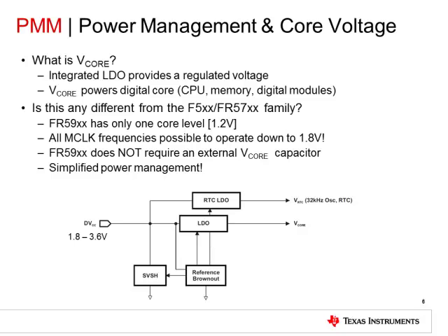The Power Management Module, or PMM, manages all functions related to the power supply and its supervision for the device. Its primary functions are first to generate a supply voltage for the core logic, and second to provide a mechanism for the supervision of both the voltage applied to the device at the DVCC pin and the internal voltage generated for the core.